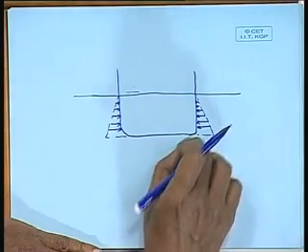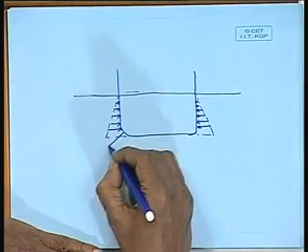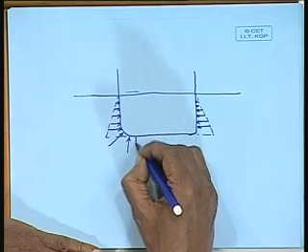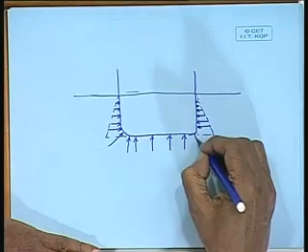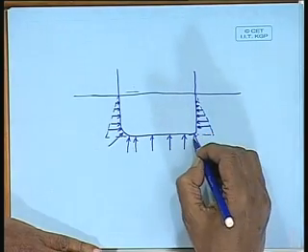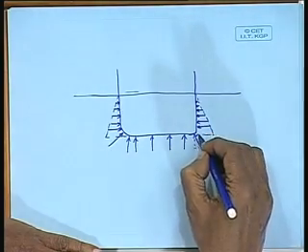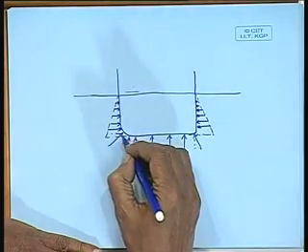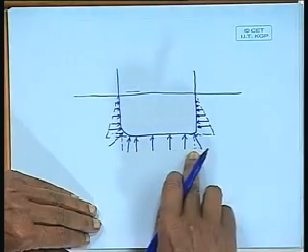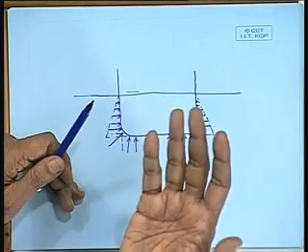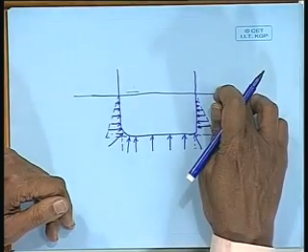But look at the bottom, what is happening? Okay. So, this will also have two components, this and this. So, these transverse components will cancel because of the symmetry of the body. So, what is existing is this pressure force which is trying to push the body up, and there is no pressure here, pressure is 0, equal to atmospheric pressure.